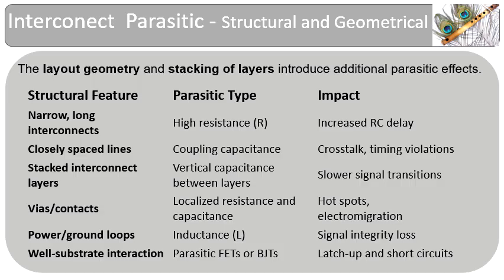Power and ground loops: poorly designed power distribution networks create loops and uneven current paths. This results in increased IR drop, ground and supply bounce, and creates an unstable power supply that impacts noise margin. This is critical for high-speed circuits and global clock nets.